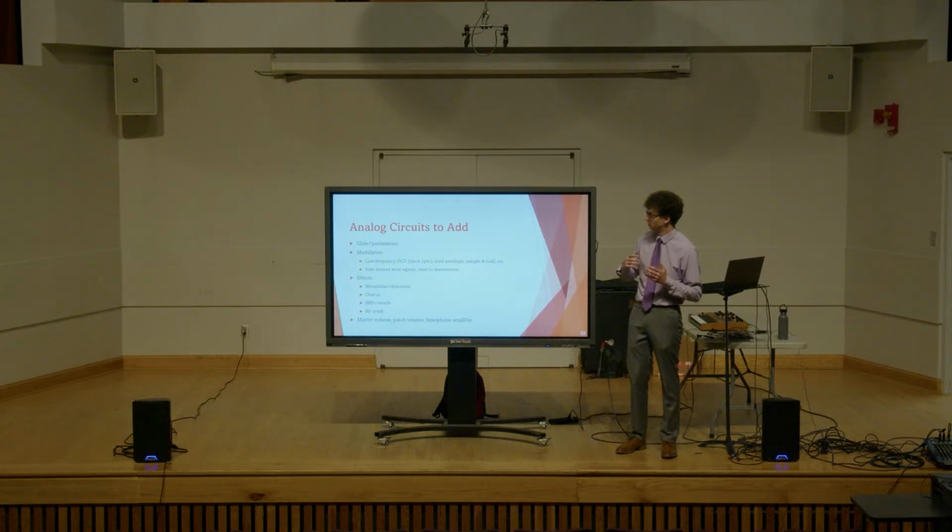And so what I'd like to, at the very least, have for modulation is a low frequency oscillator, which I intend to make a digitally controlled oscillator instead of the voltage controlled oscillators which I showed you earlier. The plus side of that would be that I can sync it to a clock. So for example, if I take a MIDI clock in that has a particular tempo, I can say, okay, I want this to oscillate at 4 times per beat or 2 times per beat, that kind of thing.